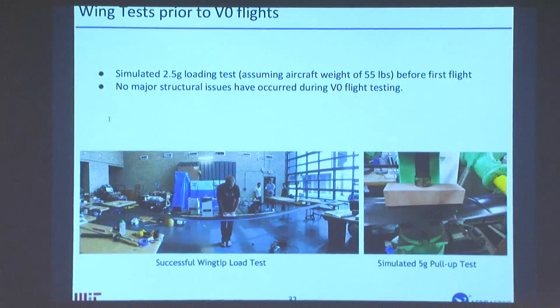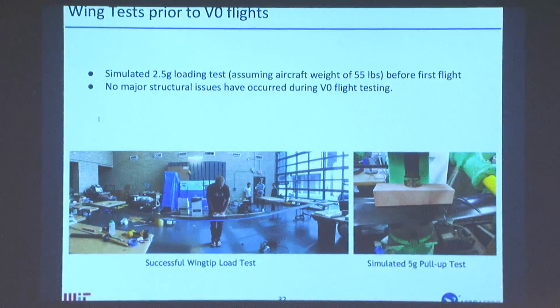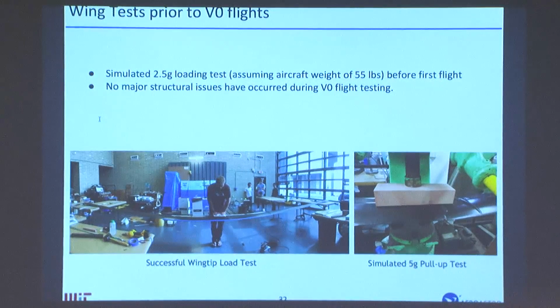But we did some critical tests. We did some testing of like critical elements that really matter, and one of those is the wing. So before we went out for our first flight, we simulated the loads, the bending loads that would be on the wing. And it turns out you can do the math to figure out the bending loads in a wing.